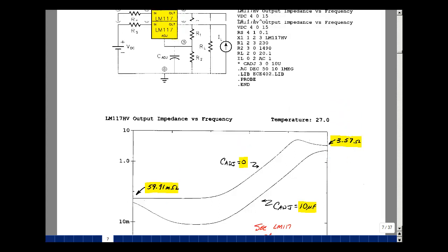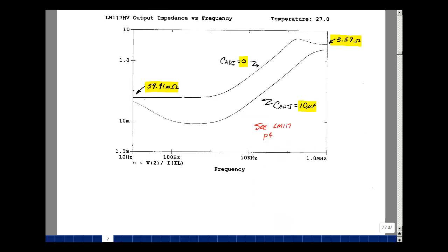Now in developing the model, what I did was try to fit these curves to the parameters I had inside the model. So the things that were dealing with DC or current limiting and things like that, I just shut off and simply used the op amp and introduced poles and zeros into the circuit so that I could match these curves. This is sort of the effect of a dominant pole, and eventually there's other poles and zeros out here. And so I was adding values of R and C's to create those effects. So my first pass on the model was to try to get the AC parameters correct. One other comment too, this is going to look very much like the data sheet, but not exactly. And again, what I wound up doing was measuring this myself and then comparing my lab data to the simulation and trying to tweak the numbers so I get those to fit.